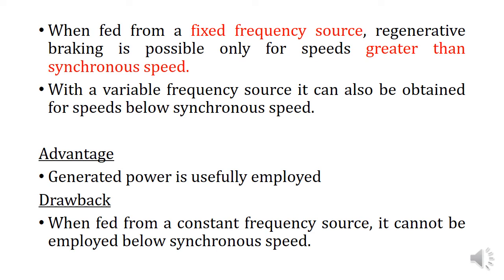Normally the machine will be operating below synchronous speed, and we have to brake the machine below synchronous speed, and that is not possible with a constant frequency source. So we have to employ a variable frequency power supply for this.